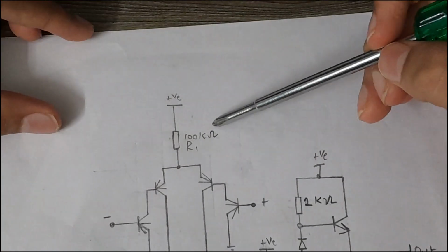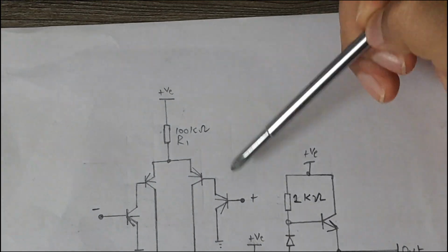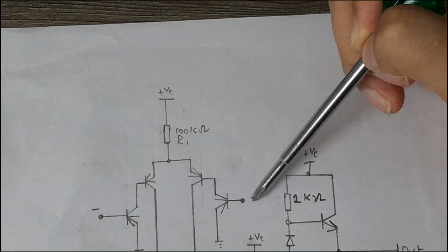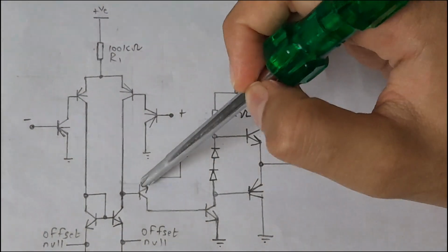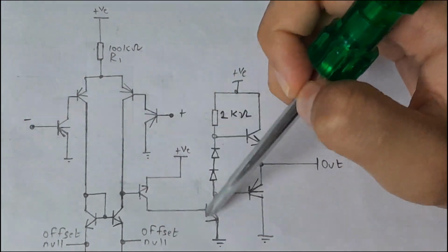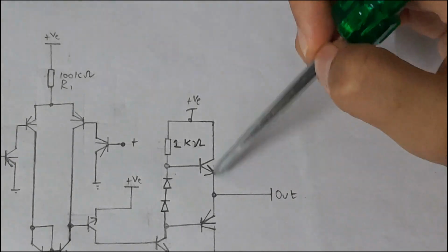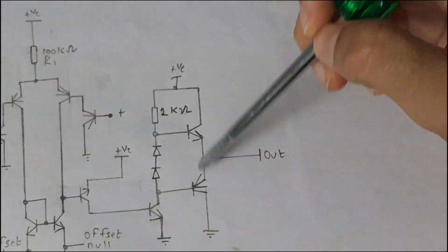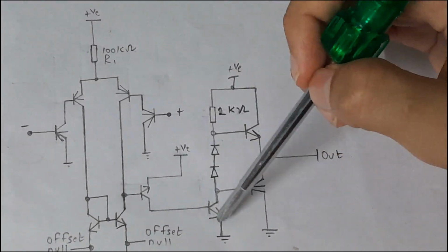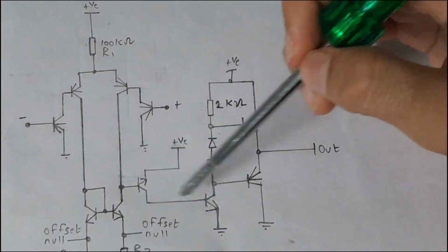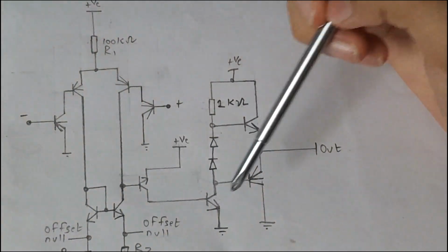We can increase the resistance to 100 kilo ohms, so there will be some microamps flowing to the base of the transistor, and we can also connect a Darlington pair at the output of the op amp, and we can connect this output stage class B amplifier, and it is gonna amplify the current, and this Darlington pair with these two transistors are gonna amplify the voltage and current.